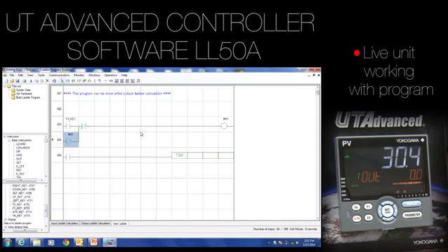So when F1 key is on, this should probably be our timer. Timer 1, because this timer here is going to run for 10 seconds. So when it elapses, it's going to change state. It's going to turn this off. So we're going to bring that on. That's going to come on, and maybe we'll have it do something else here, which would be kind of neat. So this should be M01.